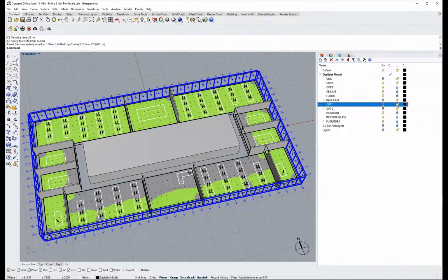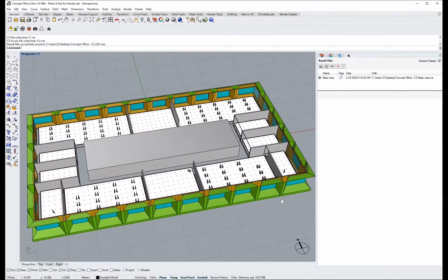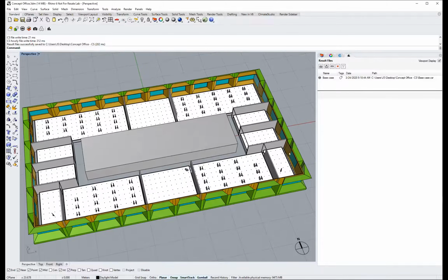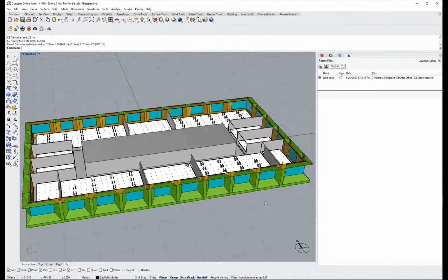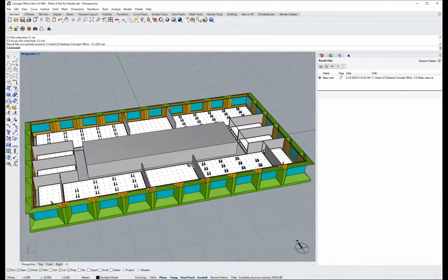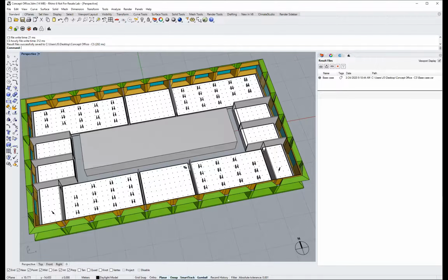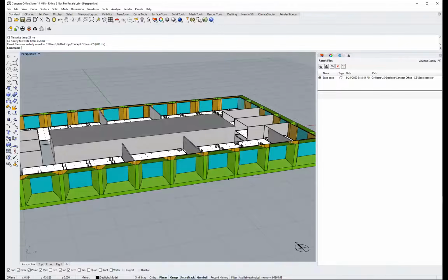I have this option one. Okay, and what this is, is a design idea about moving the structure to the exterior and then going to a punched opening facade. So I know that I had ample daylight in my base case option, and the real problem was overlighting due to direct sun. So what I'm going to do is move the structure out. This actually opens up layouts in the interior for more flexibility. And it also provides some self-shading. So where the column cladding comes around can form vertical shading, and where spandrel beams and horizontals meet them together, we get some horizontal shading as well.